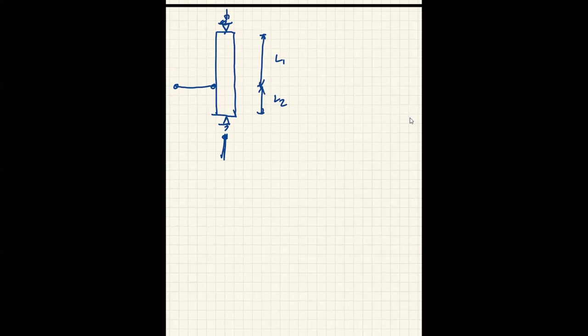Thank you very much. Now the point is this. Sometimes you cannot brace in the middle. We don't know the conditions of architecture. Sometimes the point of bracing is available to you only at some point, and you would want to use it if you could. It may look absurd on paper, where you can do what you want. Why brace so that L1 is longer than L2, right?